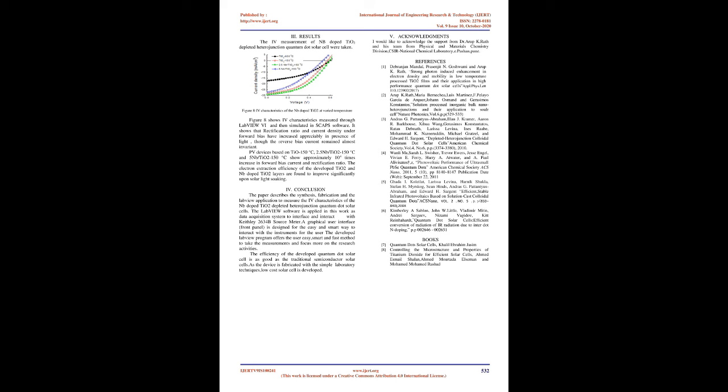When the execution exits from the loop, it enters into the SC_parameter_calculator sub-VI for the calculation of maximum power point values, VM, IM and PM, and its curve, fill factor FF, cell efficiency, current density JSC, open circuit voltage VOC, and short circuit current ISC, and displays the results on the front panel of the VI.